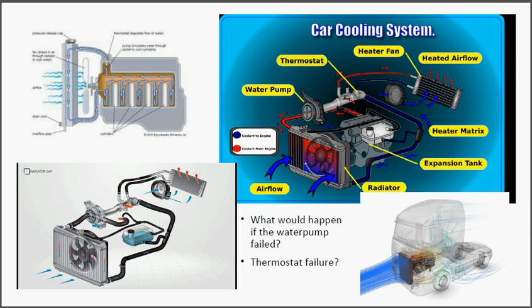And one trick to find out whether it's a thermostat fault is to check the temperature before and after the thermostat. You can just feel it with your hands, to figure out where the fault is. And again, be careful.